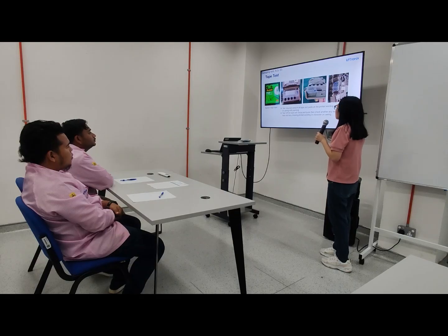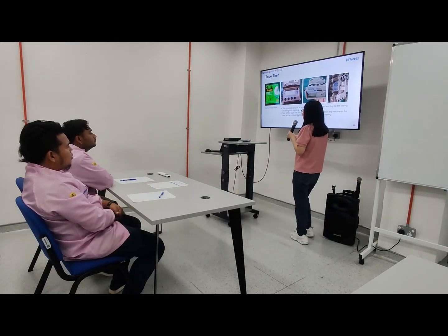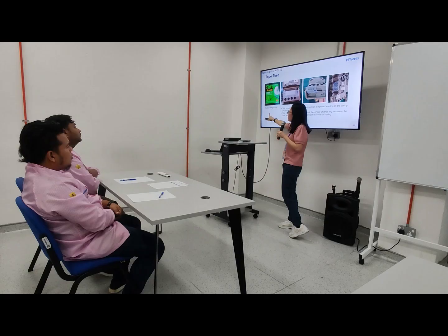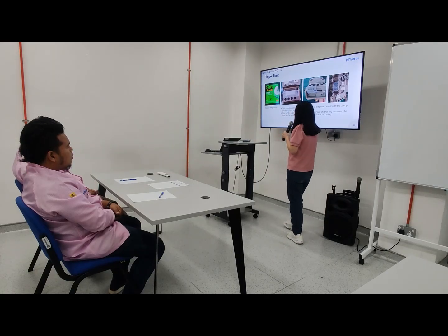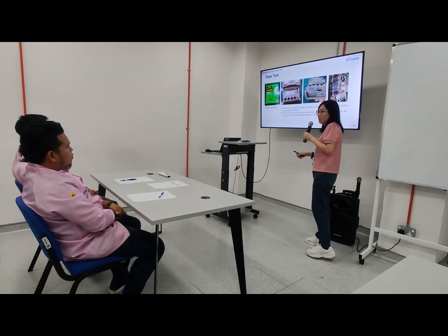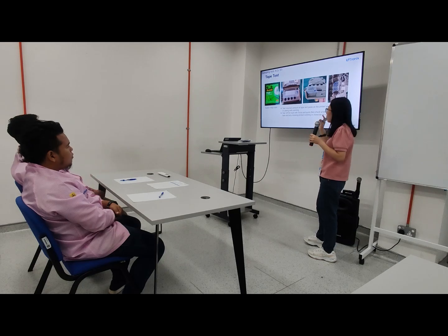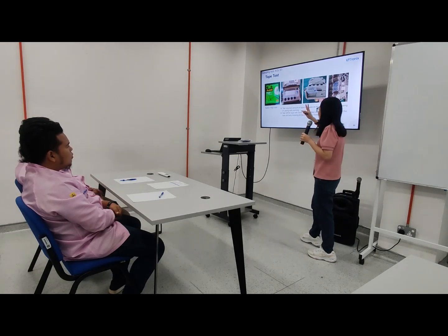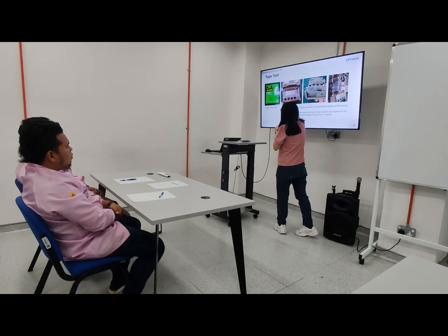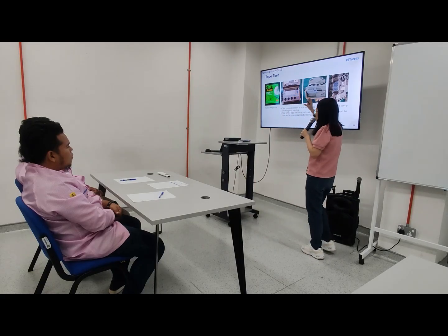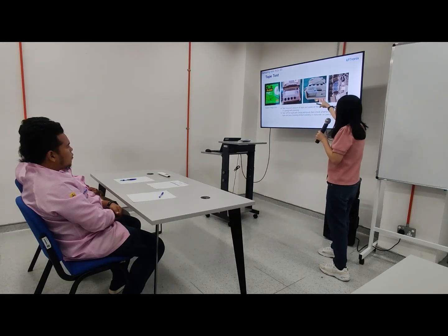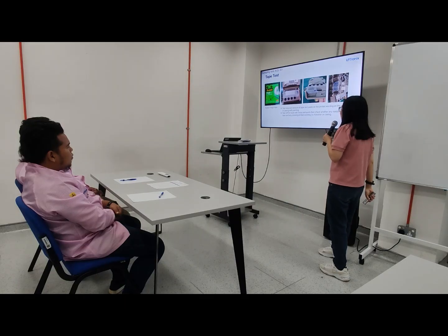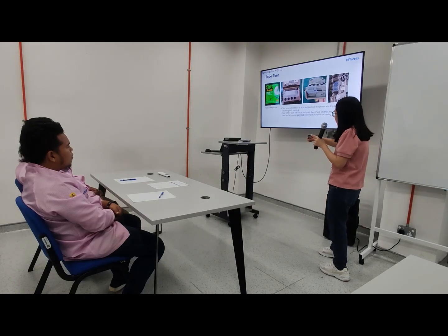Okay, tape test. This is the tape that we require to use, magic tape. This one actually is very simple. You just take off an amount of the tape and then paste it on the printed wording area. For example, here we have the menu, down, up, enter, and all the wording here, you just paste the tape on the SD card or the printing casing, and then we just take it off.